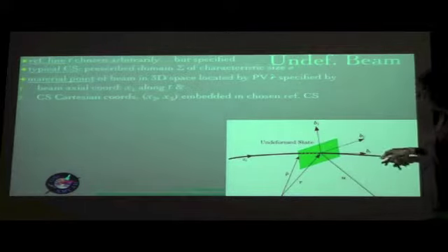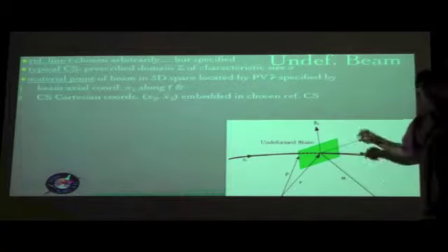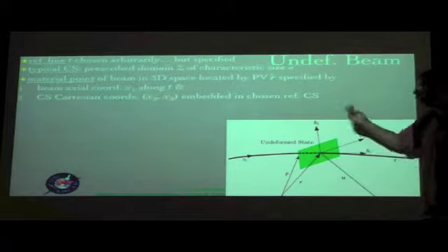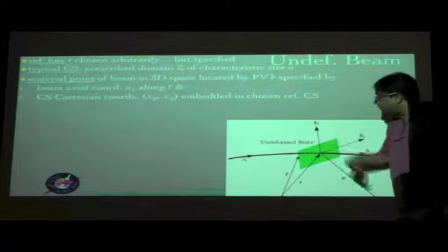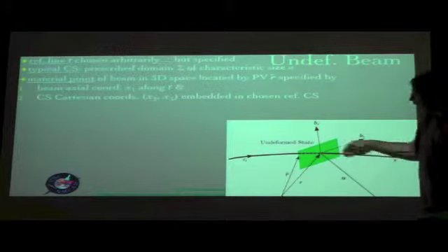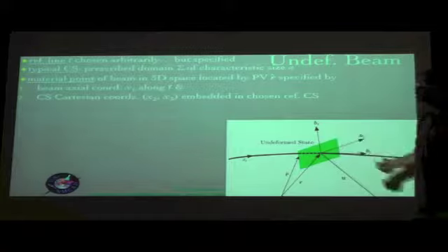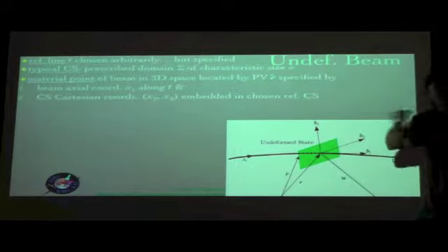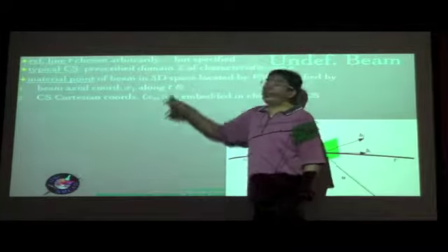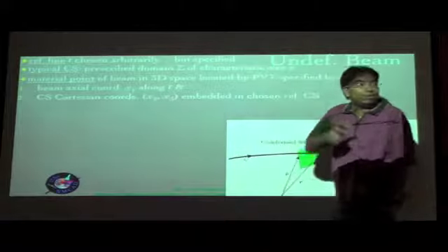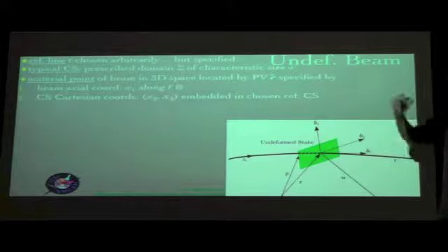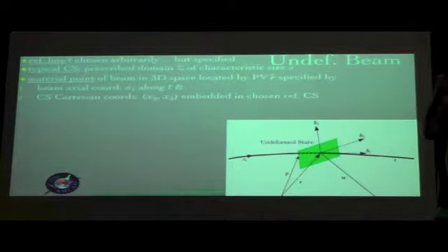So you have a reference line, and perpendicular to that, though it is also possible in general to have an oblique cross-section, which, as I said, was useful, for example, in swept wings. But right now let's focus on this. So where you don't have an oblique cross-section, but you have a normal cross-section in the undeformed state, once that cross-section is chosen, you introduce x2 and x3. Once again, you have the choice. So just like here, R can be chosen arbitrarily. The direction in which you choose x2 and x3 can also be arbitrary, just that they are perpendicular to each other, these coordinate curves because we are talking about a Cartesian coordinate system over here.